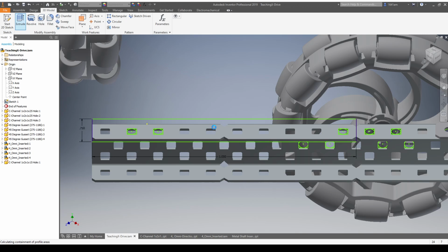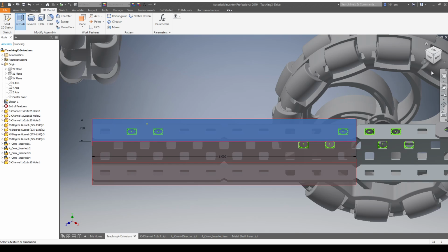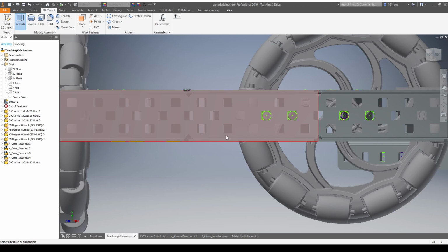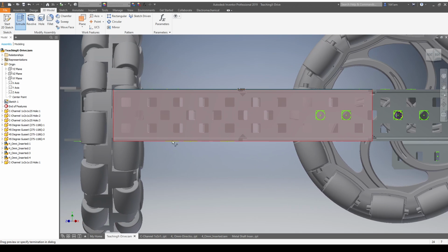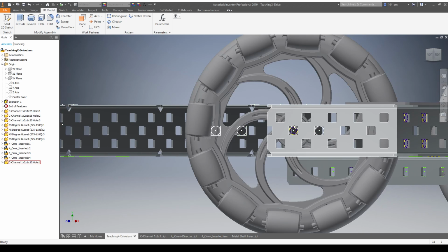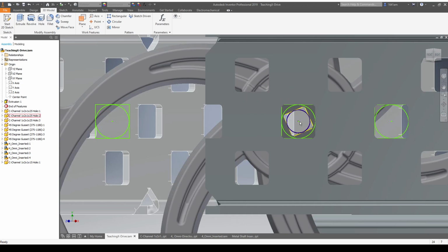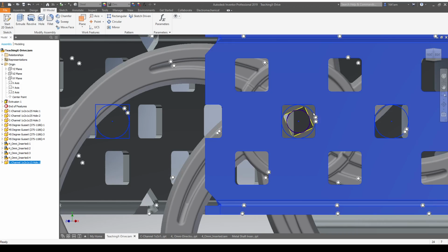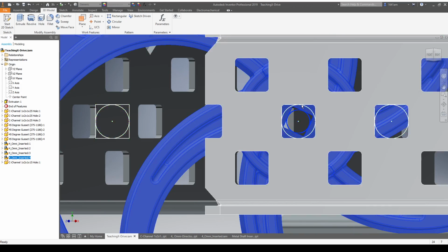And then when you hit extrude, since this is the only sketch in the feature, it'll automatically be chosen. And if you extrude it just enough that it cuts everything, which is 1 inch, then you wait for it to load, because it's cutting a feature inside. It cuts it as if you had cut the piece of metal in real life. So as you can see, we only need that last hole where the wheel is, so that it can rotate about that.